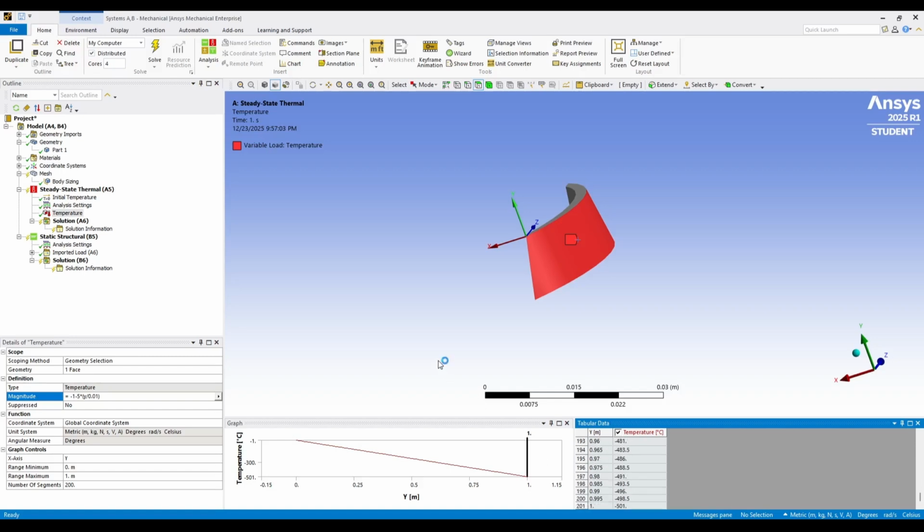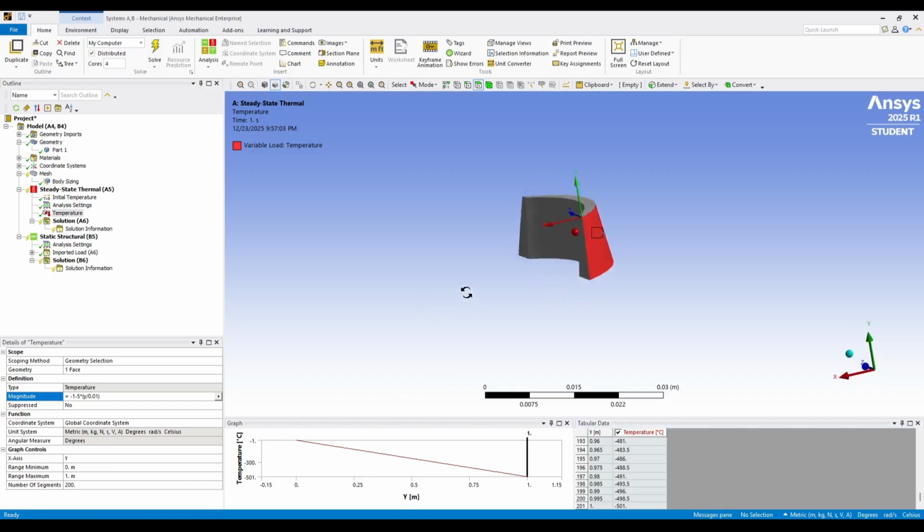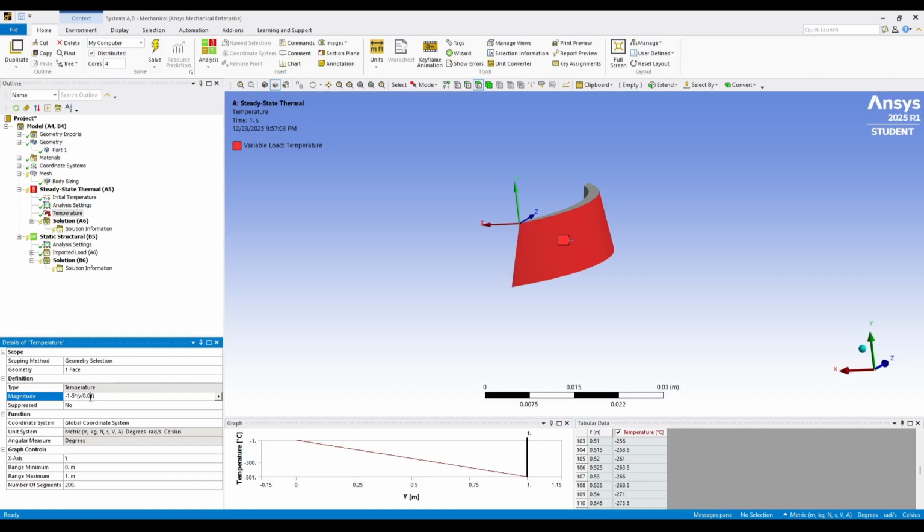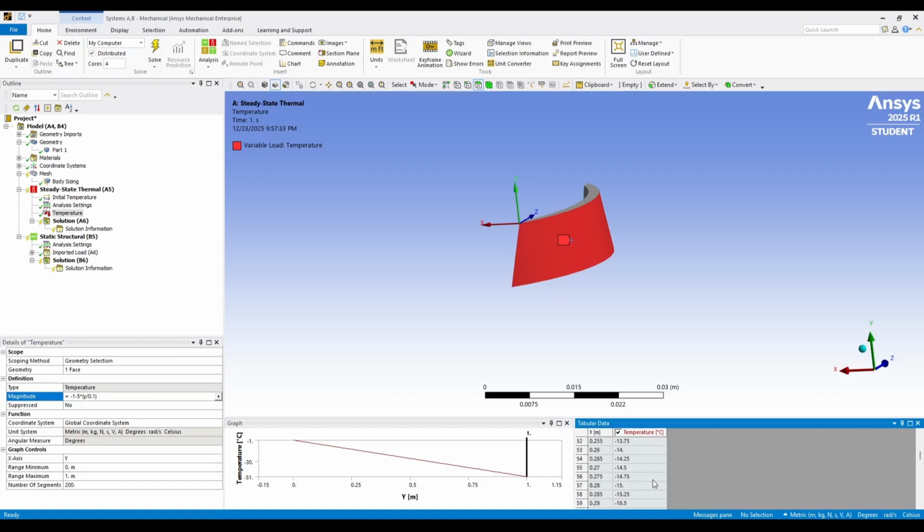These thermal stresses combine with stresses from hydrostatic pressure and self-weight, creating a more realistic stress condition than structural analysis alone. The results show that temperature changes can noticeably influence stress levels, especially near the base and curved abutment regions where movement is restricted.